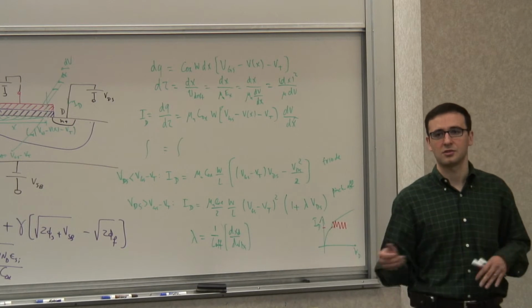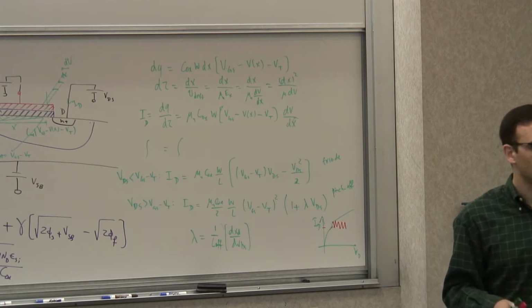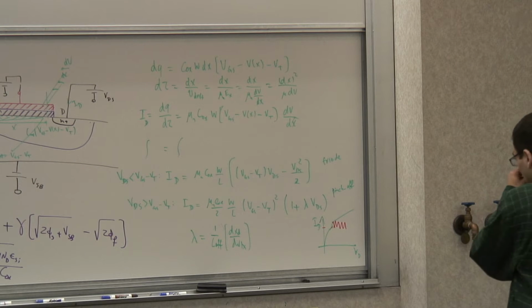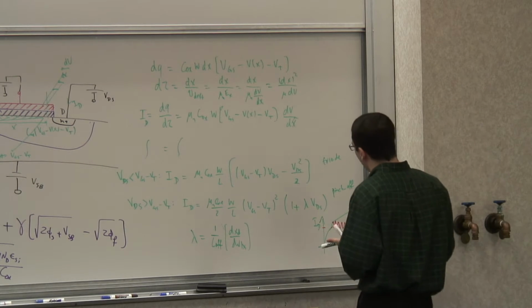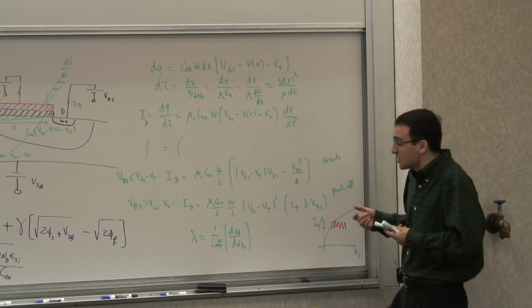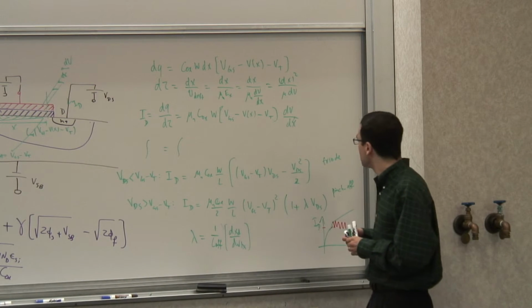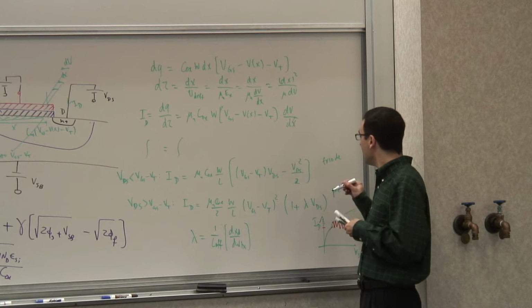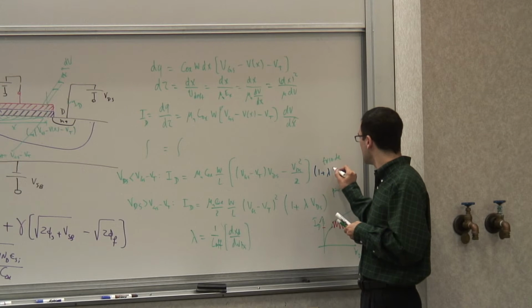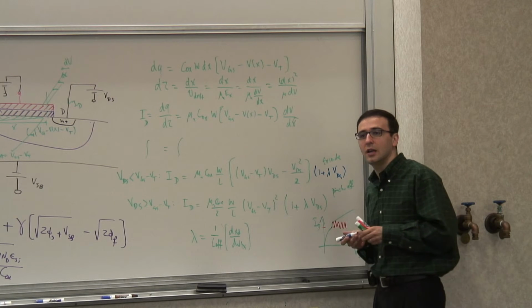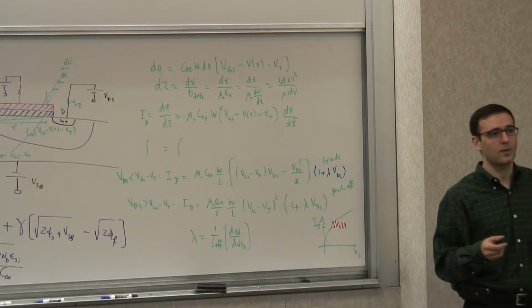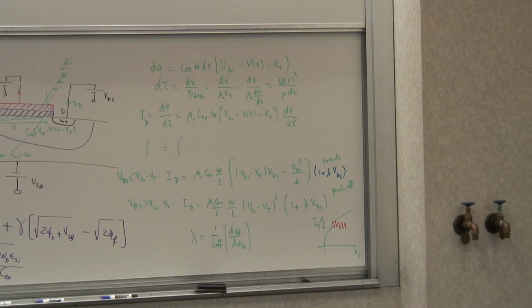And then it gives you a convergence problem, or kind of stops working, depending on how it's written. So in simulators, it's extremely important to have this continuity. So sometimes, if you want to use this simplified equation, you may want to have a modification here too. You just may want to add that term here in your simulator. And if you put it there, then it becomes continuous. You basically just multiply both of them by this expression.